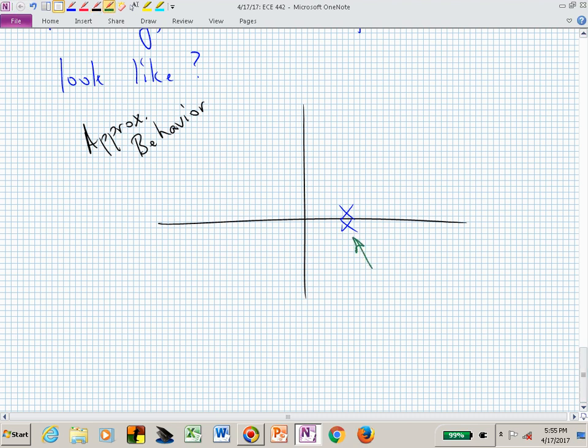Where they are located, we'll say, is at the centroid. And if these are now two poles and you had to sketch the root locus for this, what would you do? If you had to sketch the root locus diagram for this pattern of poles and zeros, what would it look like? This would just be our standard plus and minus 90, would it not? Because there's an even number of poles right on top of each other, no part of the real line belongs on the root locus. As soon as you start changing the gain k, they would have to go off the real line.